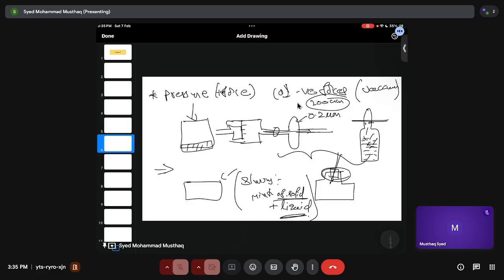Now you apply pressure here. They pass through some filters, and this filter makes sure only liquid is allowed, and the solids remain as they are. And there are vacuum filters also. There are mechanical pressure filters too, which use a mechanical pressure. We call it a tube press. And then we apply vacuum.